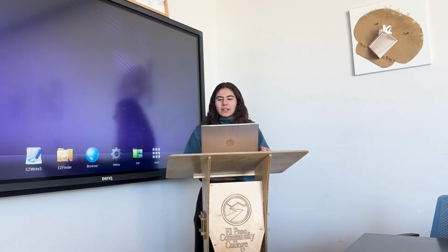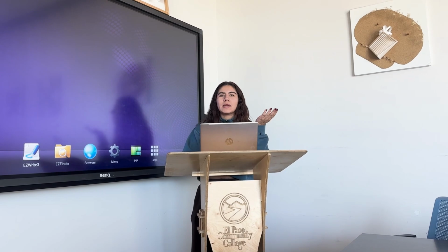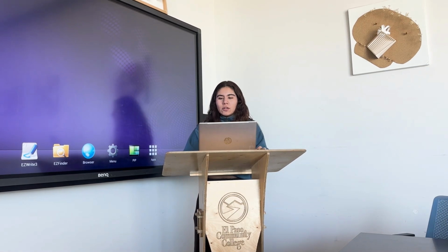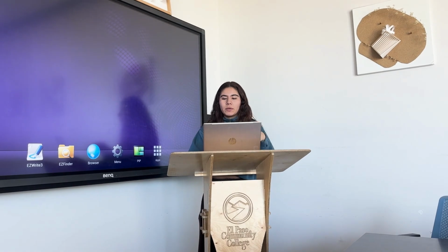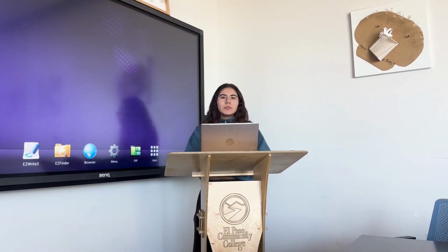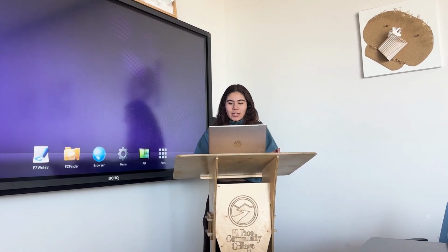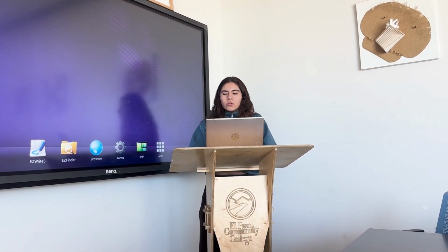To prevent insects from taking up residence within the cavity, by this I mean insects living in the cavity, stainless steel wool, or plastic or metal screens are inserted into the open joints. Weeps may also be formed with plastic tubes laid in the head joints as they are mortared, and masonry flashings are used 2 ways.